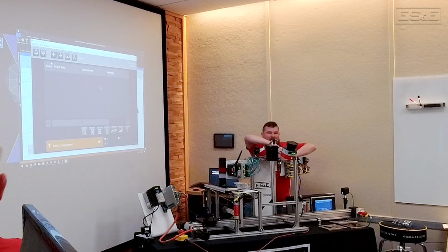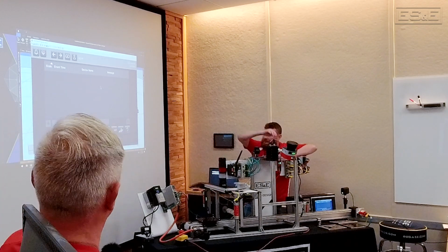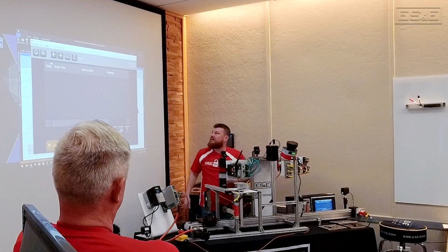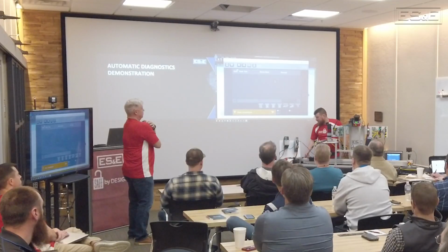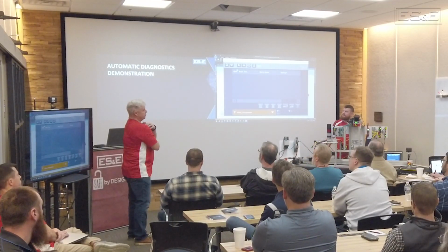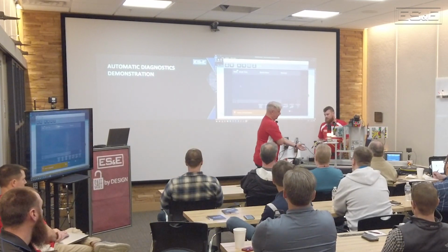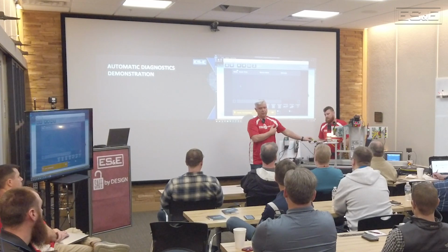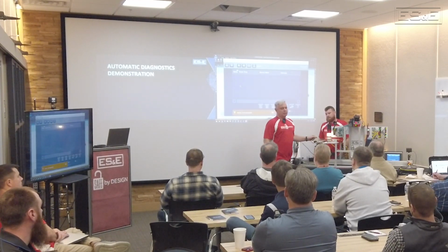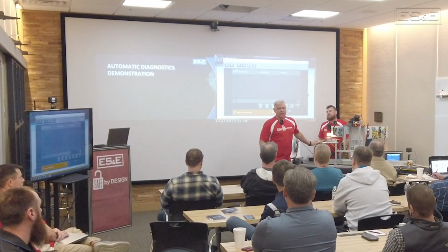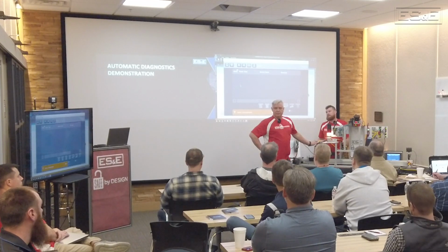And then again, once that circuit is complete, we'll go back to normal operating conditions. So one of the other things real quick on this: when Robbie first did the photo eye, how is the photo eye connected to the PLC? I know you guys don't. I/O link. So it not only does things on Ethernet, but it does it on I/O link too, right?